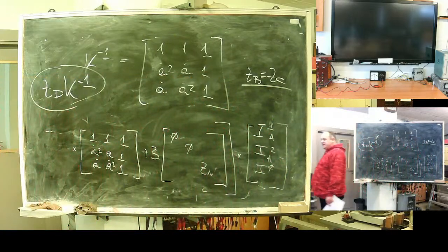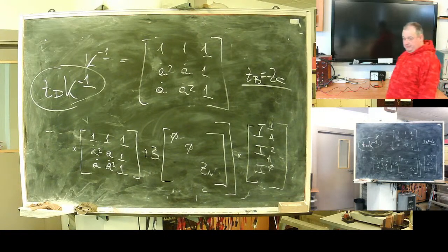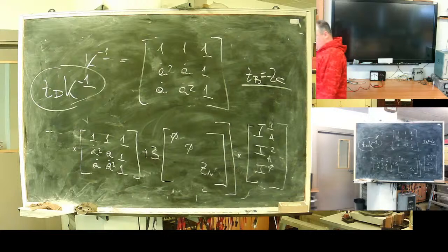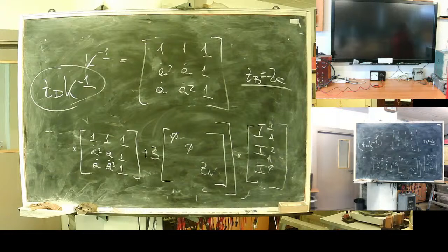In such a case, this term, the diagonal resistance matrix multiplied by the inversion of the Fortescue transform matrix, will produce a matrix with real elements that can be substituted, and this will yield a real physical network.